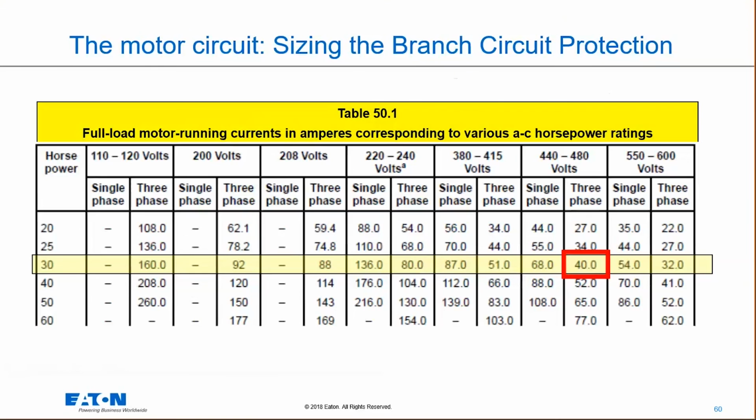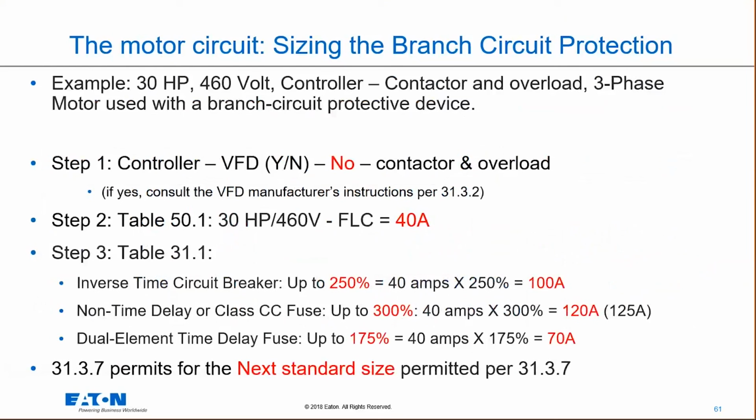So if I go back to my calculations, not terribly difficult calculations, but there's one little caveat I just want to talk about. When we look at, in this example, a 30 horsepower, 460 volt controller and contactor and overload, we have, first step, is it controlled by a VFD?